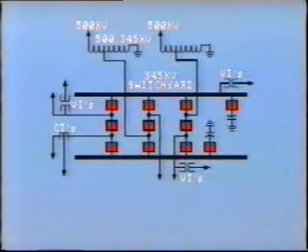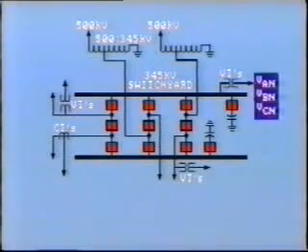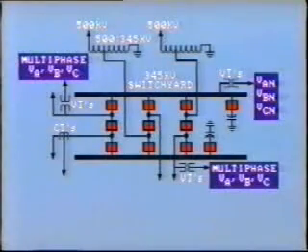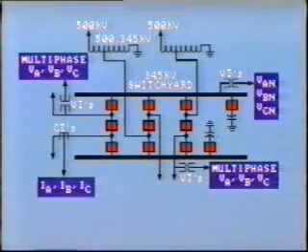Multiphasing comes in handy when we wish to monitor voltages on individual lines in addition to the bus voltage. A common arrangement would be to use a separate channel for each phase to neutral bus voltage, and then multi-phase selected line voltages. It's also important to look at phase current in each transmission line.